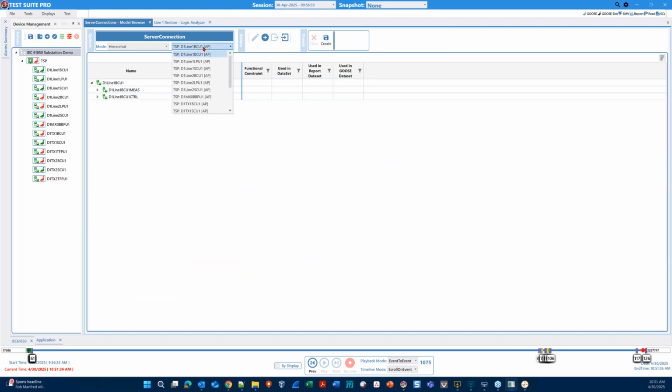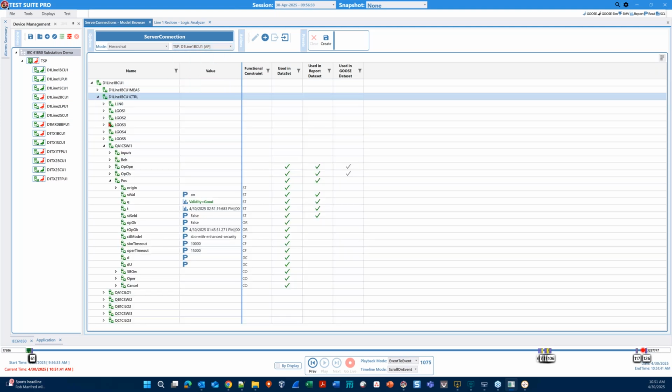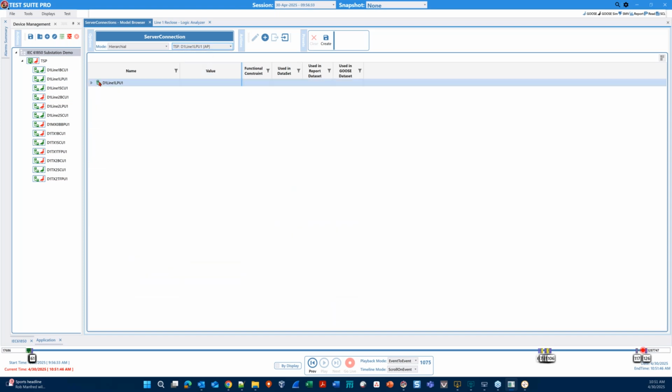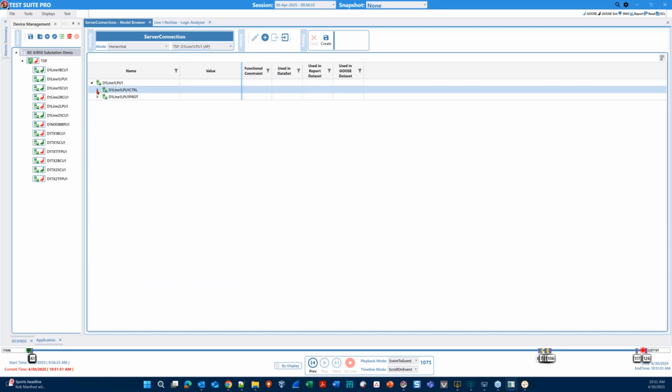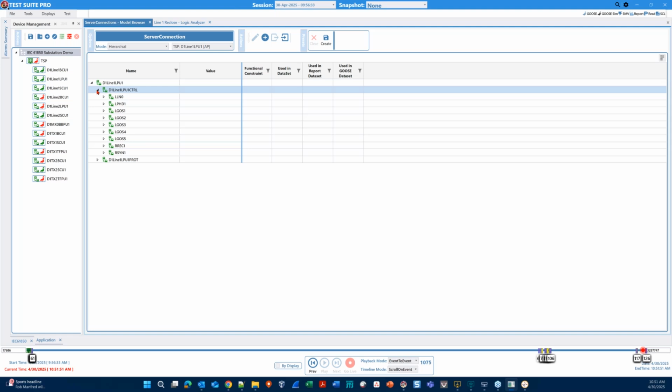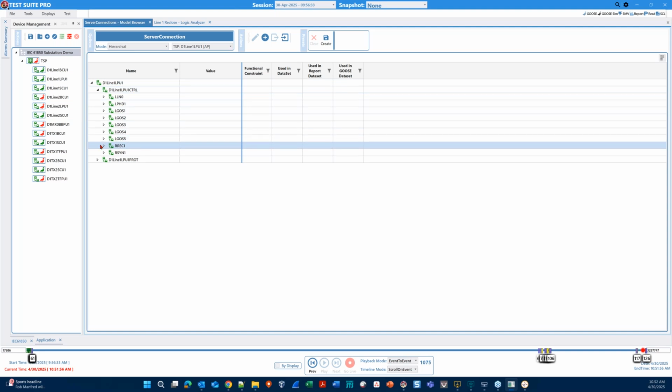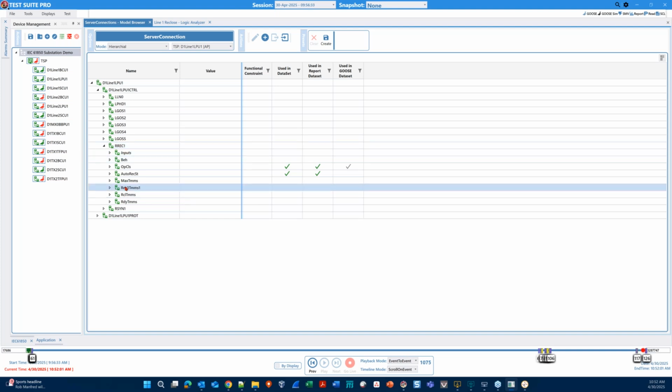So finally, I want to switch back over to our LPU, or line protection unit. Again, we had two different logical devices on this device, the first of which is going to be the control logical device. In that, we can see the different data objects or logical nodes that are controlling this particular bay.